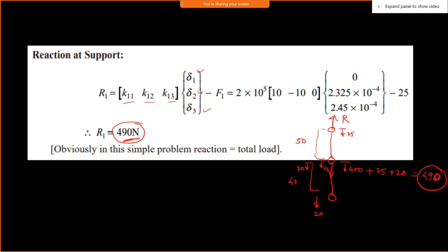That is also one type of convergence. In most FEA simulations, it is taken into account. That is force convergence. Similarly, there is another convergence, that is the deformation. In deformation convergence, we know that the displacement of node number 1 is fixed, so obviously that displacement should be equal. You can put it back into your equations, solve, and determine the u1 value. You will get the same value, 0, at that location.